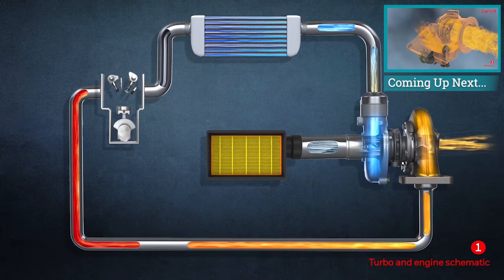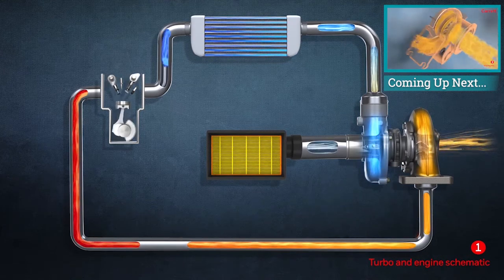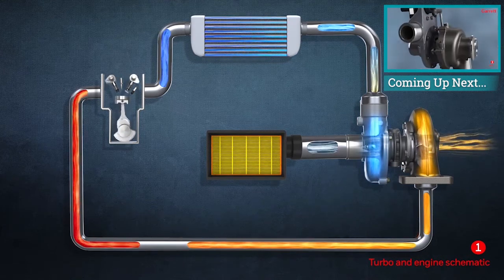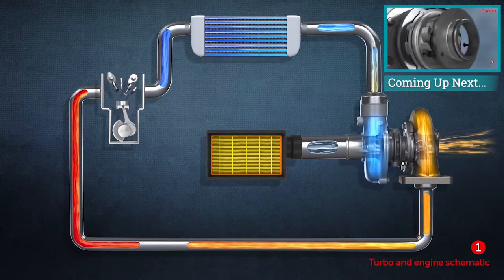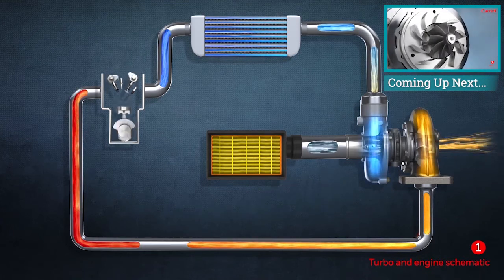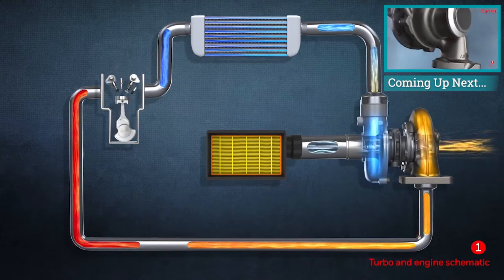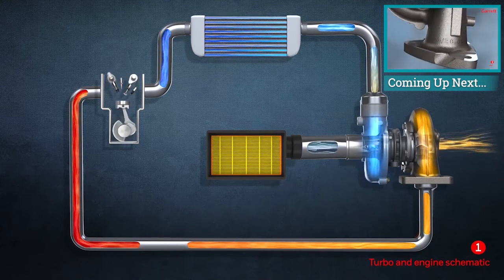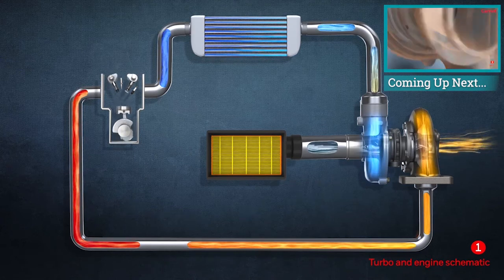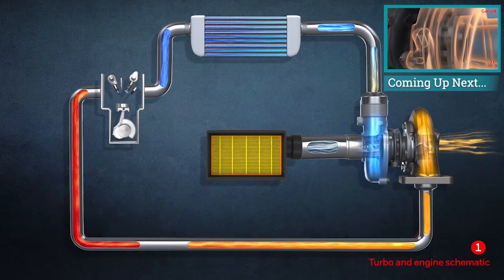Ambient air from outside the moving vehicle passes across the outside surface of these tubes and cools them to increase the density of the charge air before it enters the engine. The charge air cooler often contains many hundreds of folded metal fins, which offers a large surface area, increasing heat rejection and the efficiency of the cooling process.